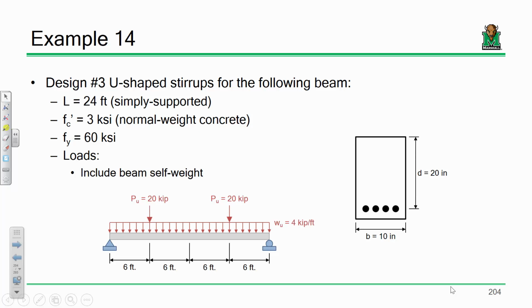Okay, now let's take this first line. What is the y-intercept of this line right here? 68. So would a fair statement for this line is that VU is 68 kips minus 4 kips per foot times x? Would that be fair? That's right, isn't it? Now, here's the kicker with this one. What is the y-intercept of this line? Can anybody tell me? 48.